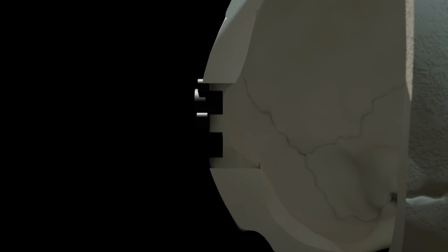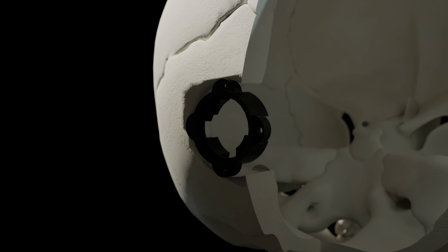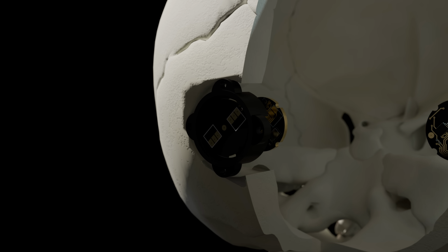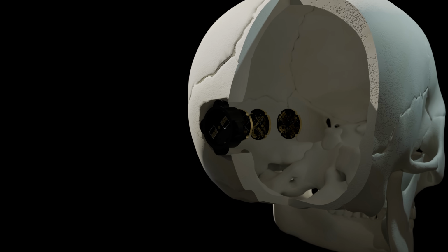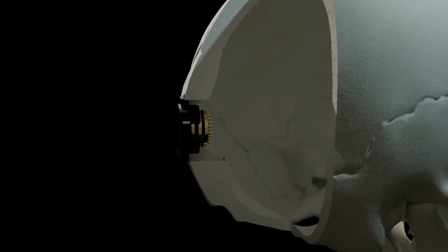I believe it is also quite important to be able to fully remove the device without any form of surgery, just a simple screwdriver, to allow for extremely simple maintenance and installing custom expansions. So I decided I would make it a circular shape, about 20mm in diameter. Now it would be essentially impossible to do anything with that scale, so it is actually a stacked design, making use of that depth of the skull. Each layer can be connected by spring pins to allow for electrical contacts and data transfer between layers.